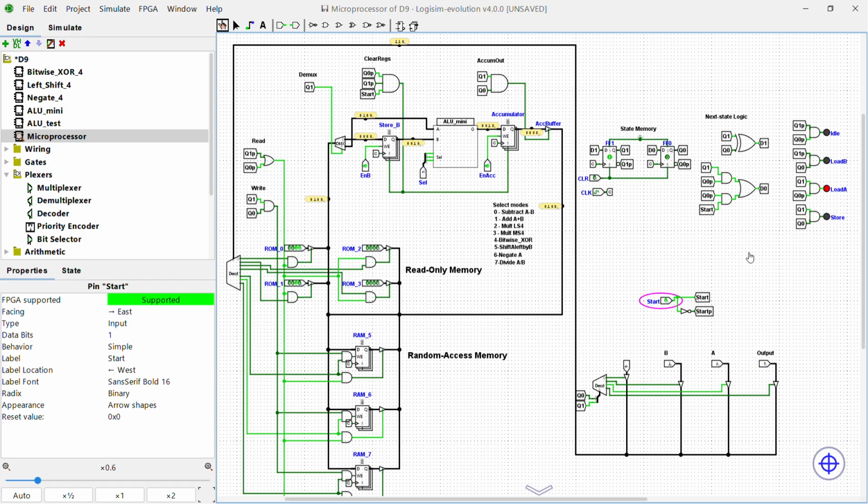My thinking while building the circuit was to first make sure the ALU worked by itself. Then I connected it into the microprocessor. After that I focused on the state machines because the processor needs the correct order: load B, load A, calculate and store. Finally I tested the circuit by checking that the first operation could save into RAM, then the second operation could reuse the saved value.